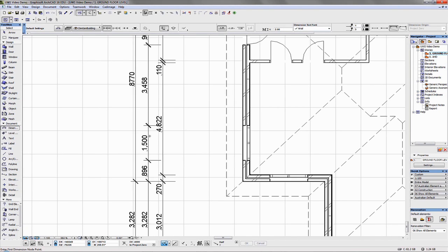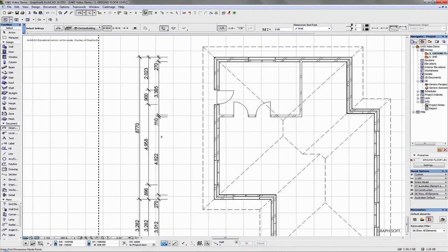You can also do things like, for example, get rid of that point and it'll amalgamate those two numbers. So I can select that point on its own. You notice this line has gone green. Hit the delete key and that has amalgamated those two numbers. You can delete a dimension altogether. So you notice the cursor will pick up the center point of these 2 points, and you can delete that whole dimension altogether. Okay. I think that's about it.